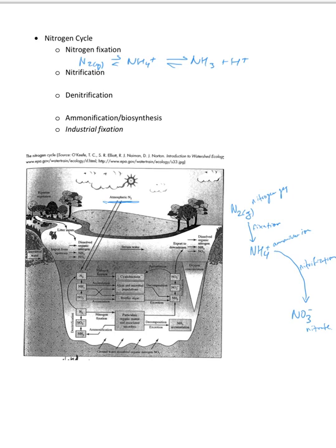And so the reaction I'm going to write up here on the top for nitrification is we take some NH4+. It also takes some bicarbonate for this to happen, 2HCO3-, and then we've got our oxygen, and that typically one-way reaction, not reversible, is going to go to NO3-, which is the nitrate, plus some carbon dioxide comes out, some water, and some energy. So again, this conversion of the nitrogen in the form of ammonium to nitrate is called nitrification.